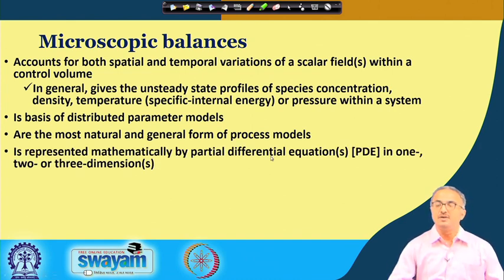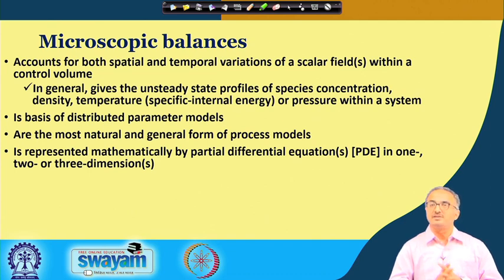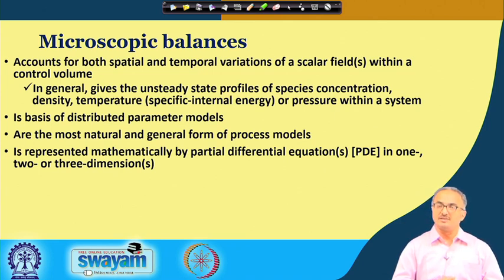And generally, whenever you are accounting for all the variations with respect to time as well as space, we will end up with partial differential equations, which is again in contrast with the ordinary differential equations we were having under the lumped parameter systems or the macroscopic balances.